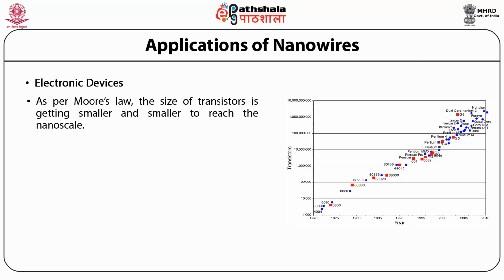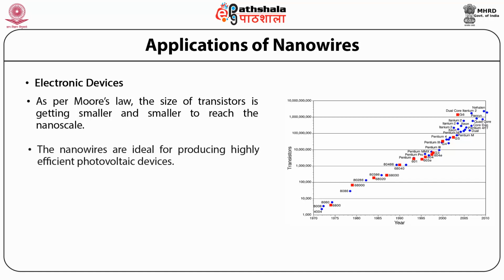However, a major challenge for nanoscale transistors is achieving high gate control over the channel. Owing to their large aspect ratios, nanowires are ideal candidates for channels in transistors. If gate dielectric is wrapped over the nanowire based channel, a high gate control over the channel electrostatic potential can be achieved, leading to efficient operation of the transistor.